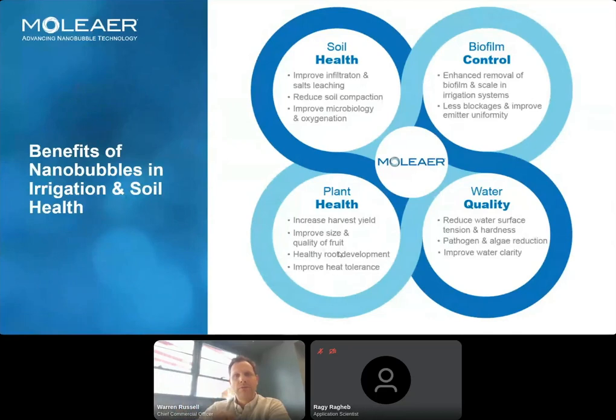Second to that, we look at biofilm control. Biofilm means two different things, one of which is you've got your irrigation system, you've got filters, you've got your emitters. It could be a drip emitter, it could be a spray emitter. What we're doing is we're using the nanobubbles to improve the hygiene of that irrigation system. That means preventing or disrupting biofilm accumulation on the surfaces. It also means preventing scale deposition on those surfaces as well.